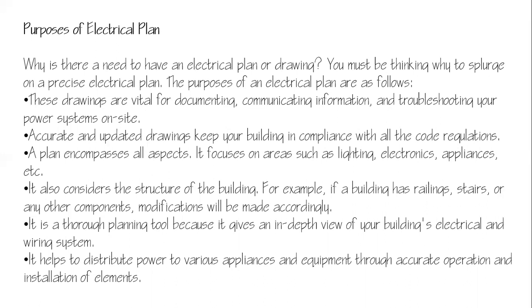So this goes well with the placement of your outlets in your space planning. If you have an air conditioning unit, then you don't put another invasive appliance on the same circuit. So that's a separate circuit. That's how you plan the distribution of the power usage of your appliances. And if you have a range or grill in your kitchen, that goes on a separate circuit.